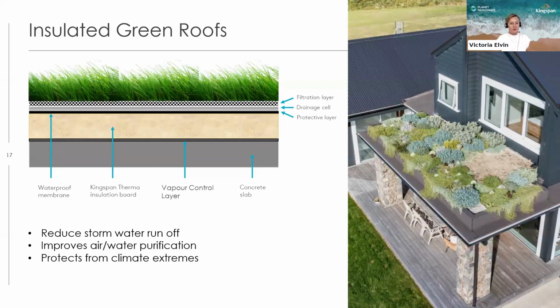Also known as garden roofs or living roofs, these proprietary systems vary on planting methodology and design requirements. There are very strict design requirements for the vegetation, the type and the root structure, and the weight of the system. It needs to be considered early in design because the structure needs to accommodate that weight of both wet soil, dry soil, plants as they're grown, and so on.